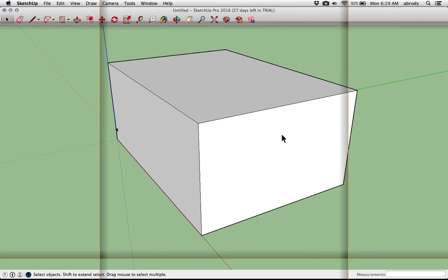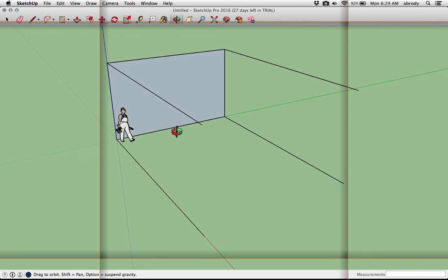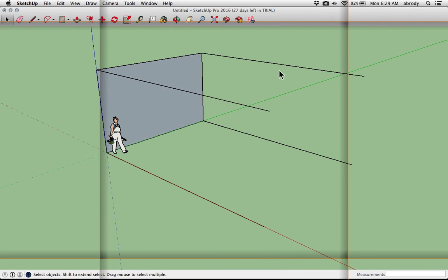To show you something, when you single click on an object, you get just the surface. If you double click on an object, you get the surface and its bounding edges. And when I delete that, you see what happens? It actually deletes the surfaces up here. A surface always needs a boundary in SketchUp. And in fact, if I want to recreate one of these surfaces, I can just draw from endpoint to endpoint, completing the boundary, and then that completes the surface.